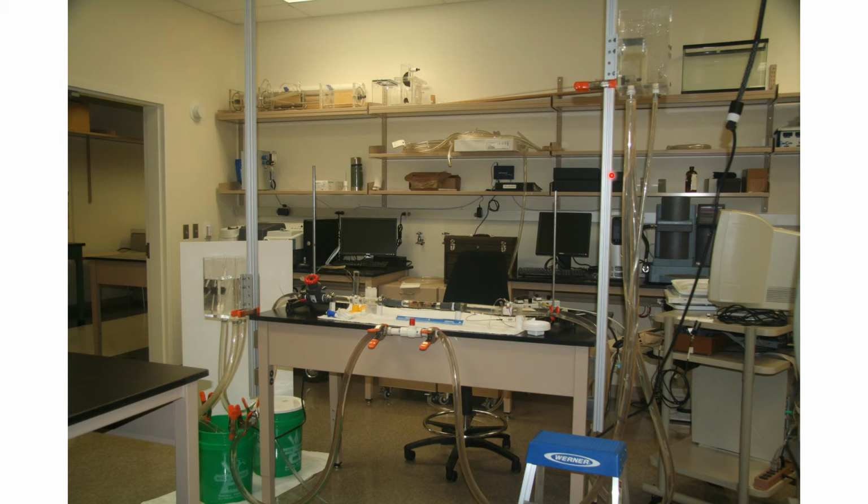Another thing is that I used large tubes to make sure that I would not have resistance through these tubes. The Reynolds numbers here will be very small, because despite the fact that the Reynolds number increases with the tube diameter, it also decreases with the velocity, and the velocity decreases with the square of the diameter.